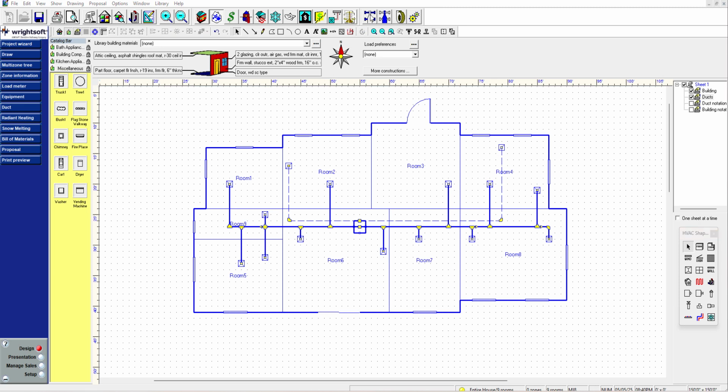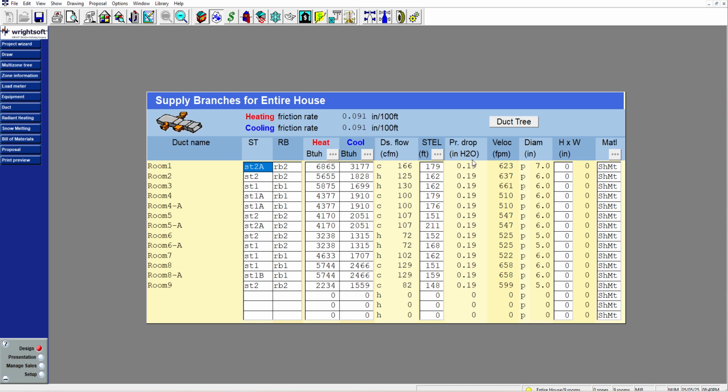We need to know the pressure drop in each, and we need to know the velocity, meaning the speed of the air moving through, and of course we need to know the diameter. So here, this would be equivalent round diameter. It's easier to calculate it from an equivalent round, meaning that the ducting is circular in shape, okay? From this circular shape, we can always convert it to what the real shape would be, okay? Like if it's rectangular, right?